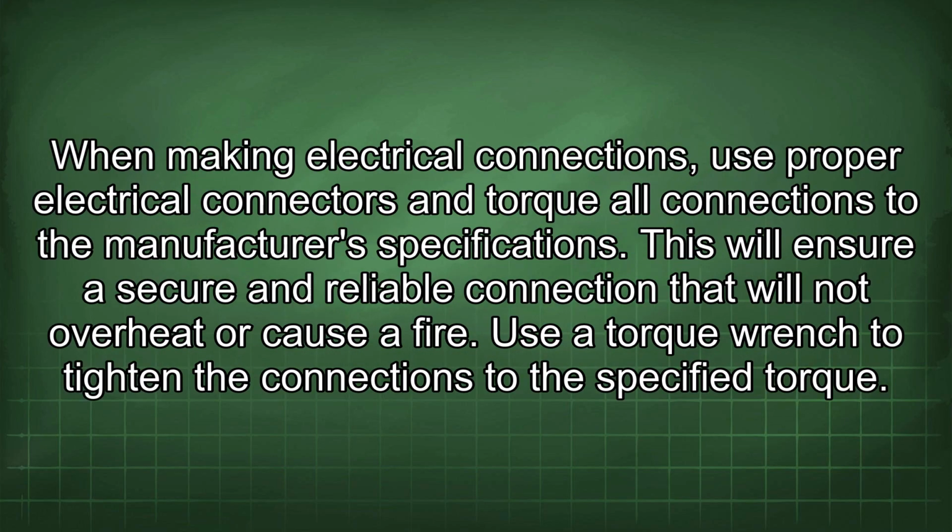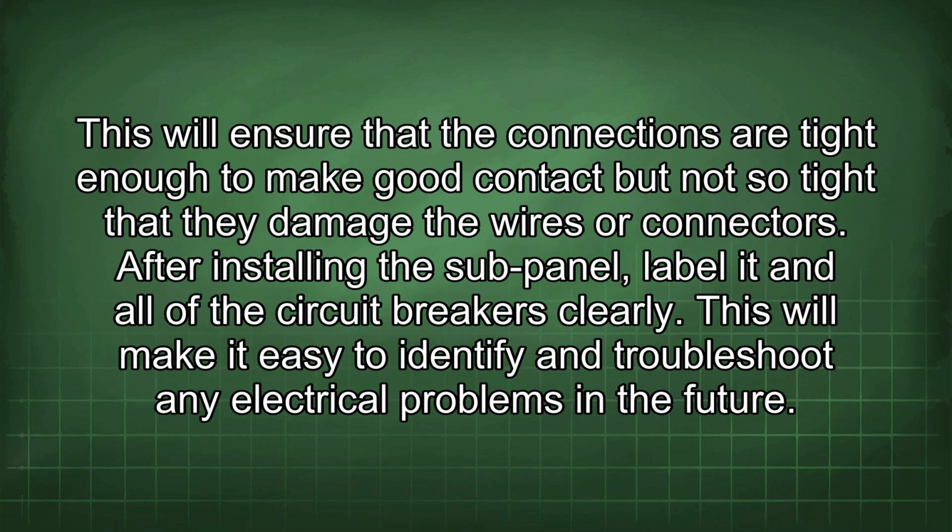When making electrical connections, use proper electrical connectors and torque all connections to the manufacturer's specifications. This will ensure a secure and reliable connection that will not overheat or cause a fire. Use a torque wrench to tighten the connections to the specified torque. This will ensure that the connections are tight enough to make good contact, but not so tight that they damage the wires or connectors.